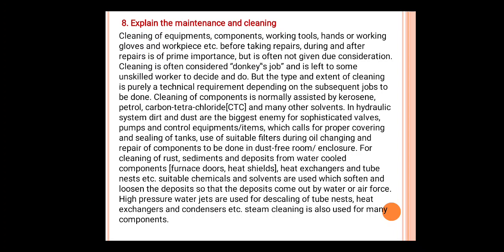Suitable chemicals and solvents are used which soften and loosen the deposits so that the deposits come out by water or air force. High pressure water jets are used for descaling of the tube nests, heat exchangers and condensers, etc. Steam cleaning is also used for many components. So cleaning plays an important role in maintenance.